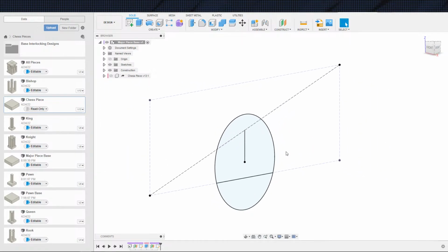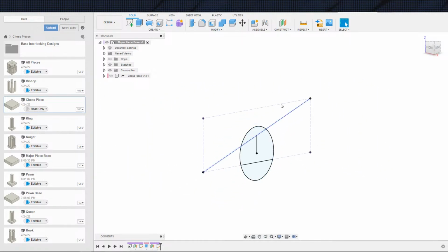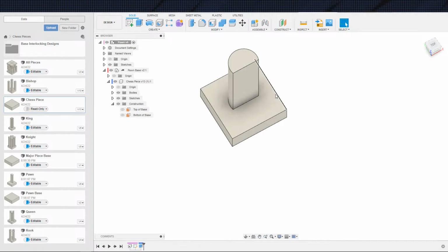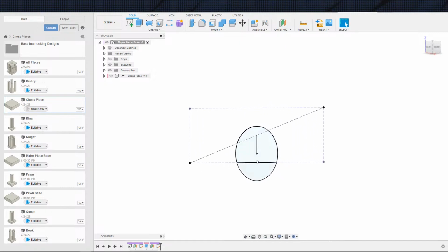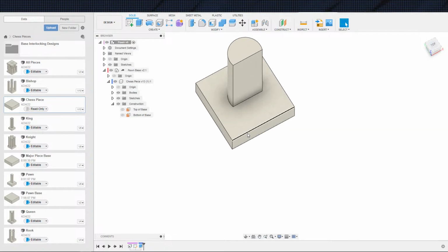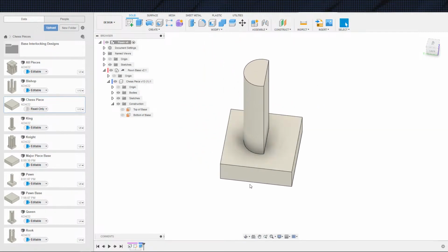The reason I wanted to put this at a different diameter is because this pawn can just slide out the side, okay? I want it to have a bulbous head so that it can't slide out. So this perpendicular hoop here is going to act as a catch, and then you've got to snap the pawn out the bottom instead of being able to just pull it out this side. So that is the idea behind it.